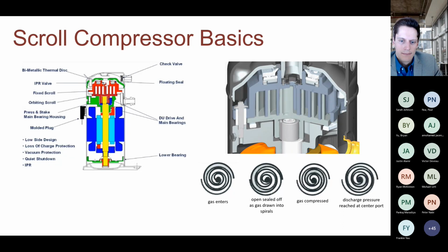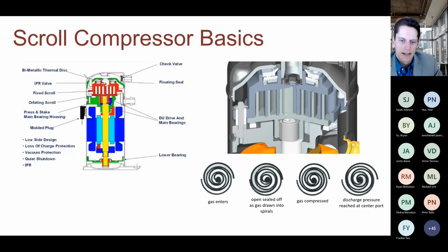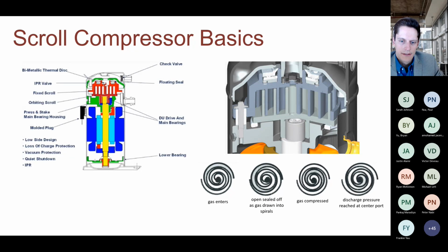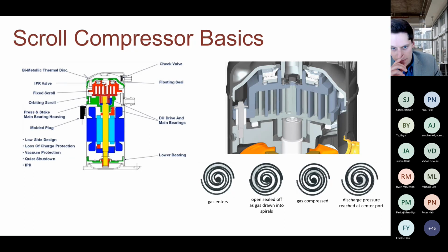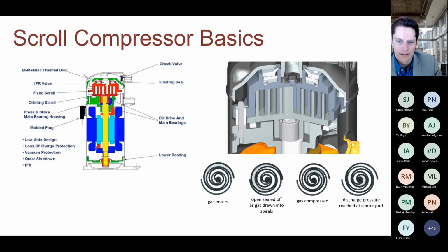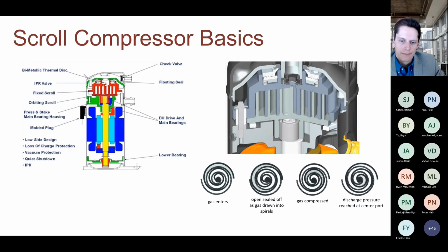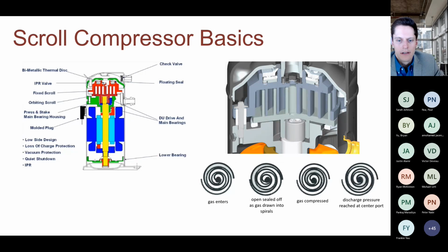And the industry is moving away from these mostly because they're not quite as efficient as an inverter compressor. And you'll see that for a digital compressor, the way it controls the capacity is it will unload or disengage. The scroll disengages every so often. You'll see the blue part rises. So that's really how it modulates, and it disengages every so often.